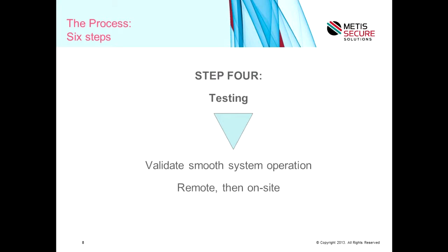The other type of testing is sort of on-site, the physical test that verifies that the appropriate text or voice announcement is being made at the appropriate place, so that the notifications can be heard clearly and can be seen easily, so that the impact at the site is what you want it to be.